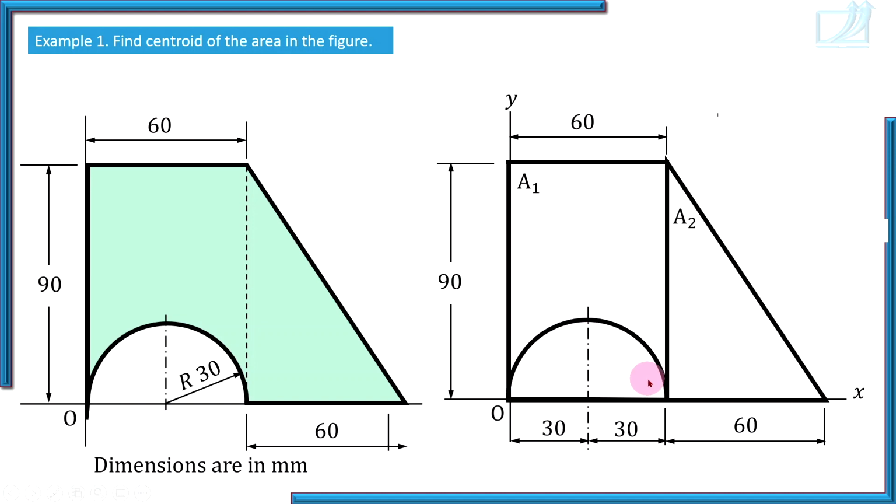When you draw a semicircle, always draw its axis of symmetry. Always, the word I have used. Always draw its axis of symmetry and insert radius along its straight edge. Watch here in the given diagram, radius is inserted using an inclined arrow. But to solve problems, it is always better to insert a radius along its straight edges.